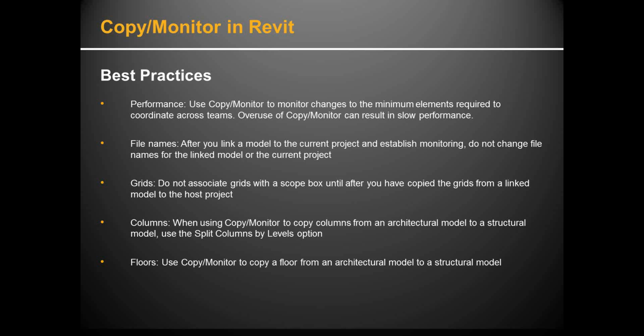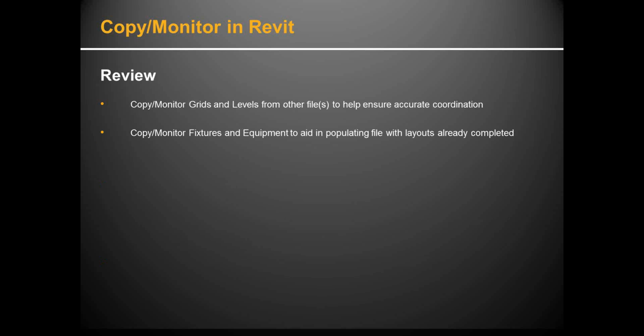I'm just going to skip over the rest of those for right now and do a quick review, which is very simple. The first part of this, I copy monitored levels and grids, just levels and grids, especially levels. If you're not copy monitoring levels, you may really want to consider that.